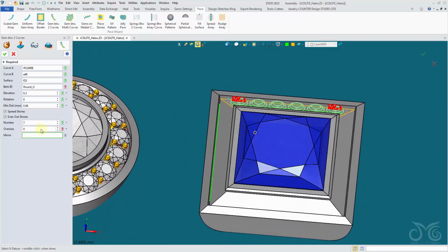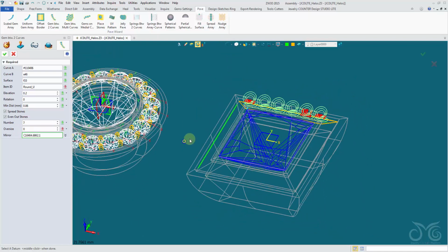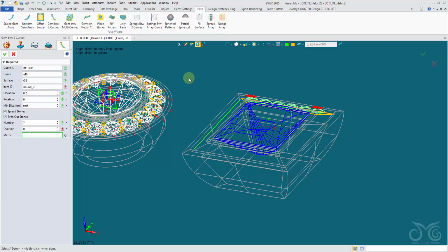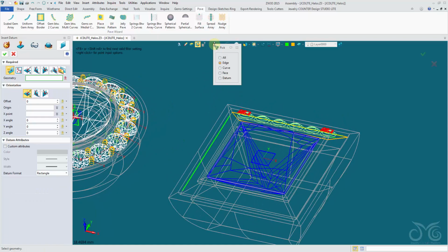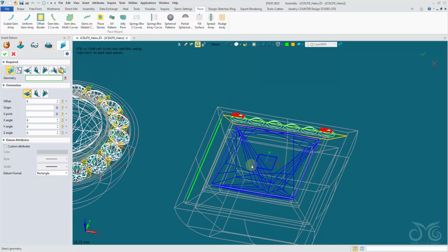these gemstones. Now we want to mirror them across a datum here, but we don't have that datum. I should have copied it along with our top datum, but it's not a problem. We can simply right click whilst we're in the mirror field, right click, insert datum. Let's swap my entity filter onto datum. Use our smart datum method. Pick at this datum here.